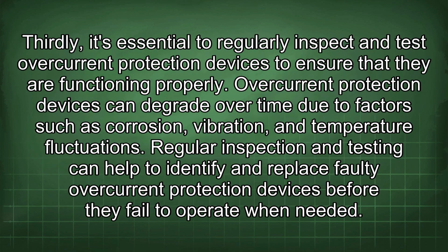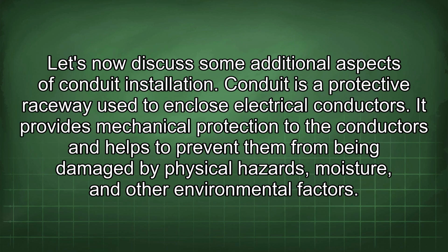Thirdly, it's essential to regularly inspect and test overcurrent protection devices to ensure that they are functioning properly. Overcurrent protection devices can degrade over time due to factors such as corrosion, vibration, and temperature fluctuations. Regular inspection and testing can help to identify and replace faulty overcurrent protection devices before they fail to operate when needed. Let's now discuss some additional aspects of conduit installation.